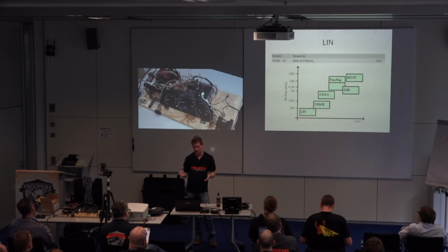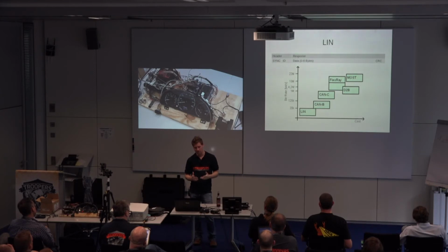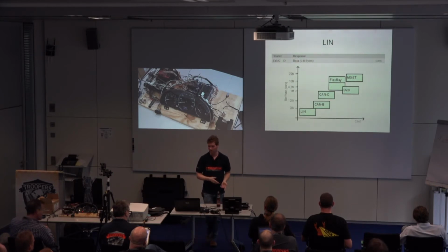So this CAN bus, being that it doesn't have a sender or a receiver, a bus, if you're familiar with networking, is very similar to a network hub. Everybody sees everybody's packets. So not having a source or a destination and everybody seeing everybody's packets makes it very, very easy to be whoever you want to be. And so from a security perspective, that's kind of what people typically manipulate.